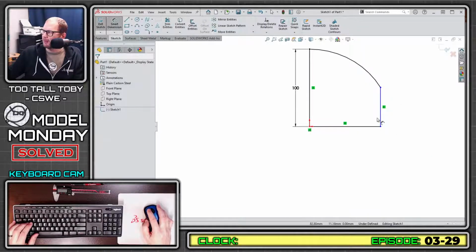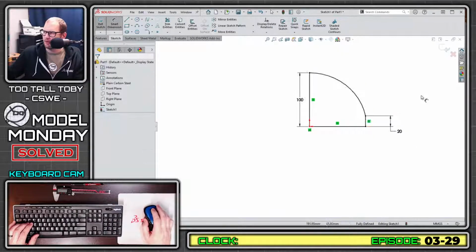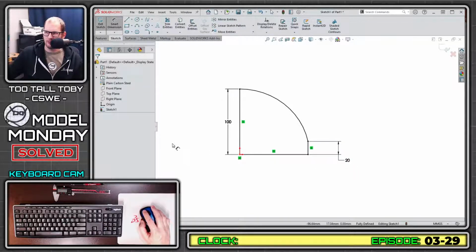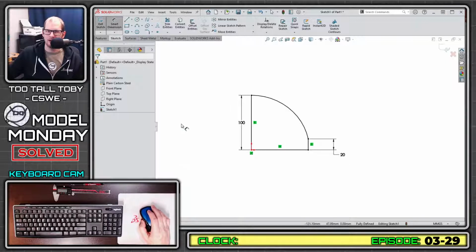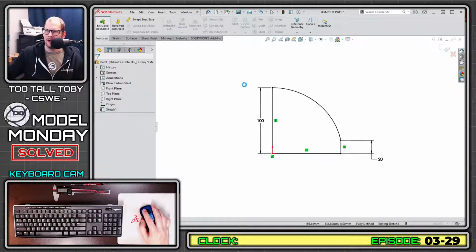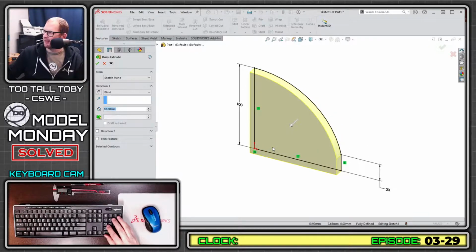And then I just need to put in the height there, which is a height of 20, and that should fully constrain that sketch. A big reason why this is nice and fully constrained is, one, I'm keeping it simple. I'm not putting the flat spot up top. I'll make that as a second feature. And two, because I'm using symmetry, I'm only having to model half of this, so I don't have to worry about making these two points horizontal if I had another line over here, or any of the other additional complexities that come with modeling the whole thing instead of just doing half of it.